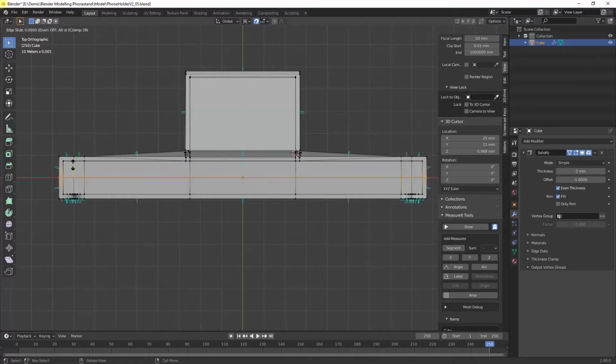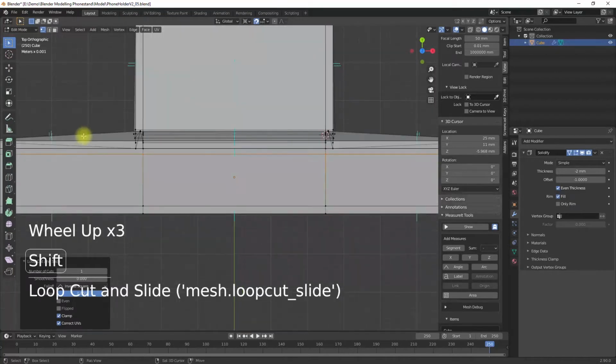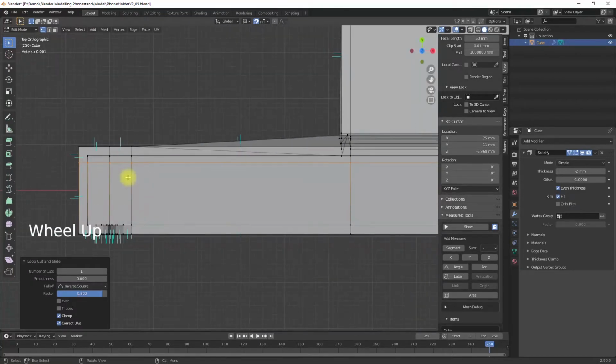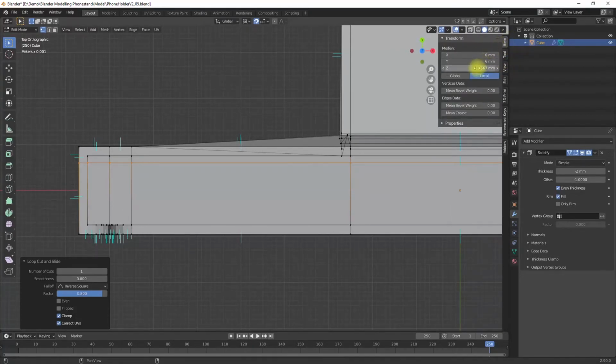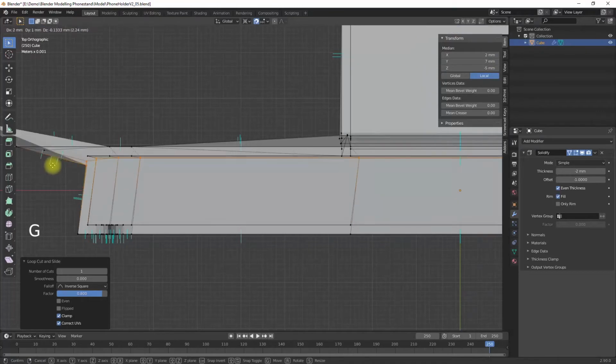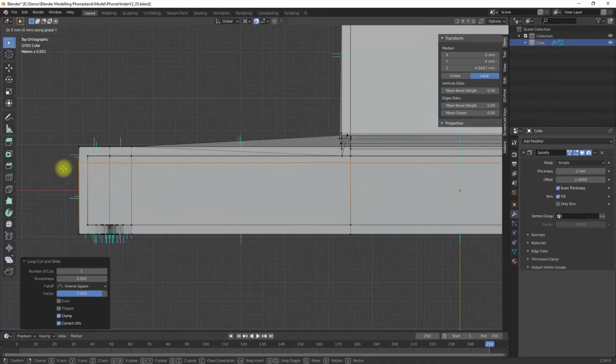There are many possibilities in Blender to round the edges of a model or to smooth the whole design. Two possibilities come immediately to my mind. First, the bevel modifier, and second, the subdivision modifier. Both modifiers are non-destructive. This means you can play around with different settings and parameters to show what it looks like without changing your model permanently.